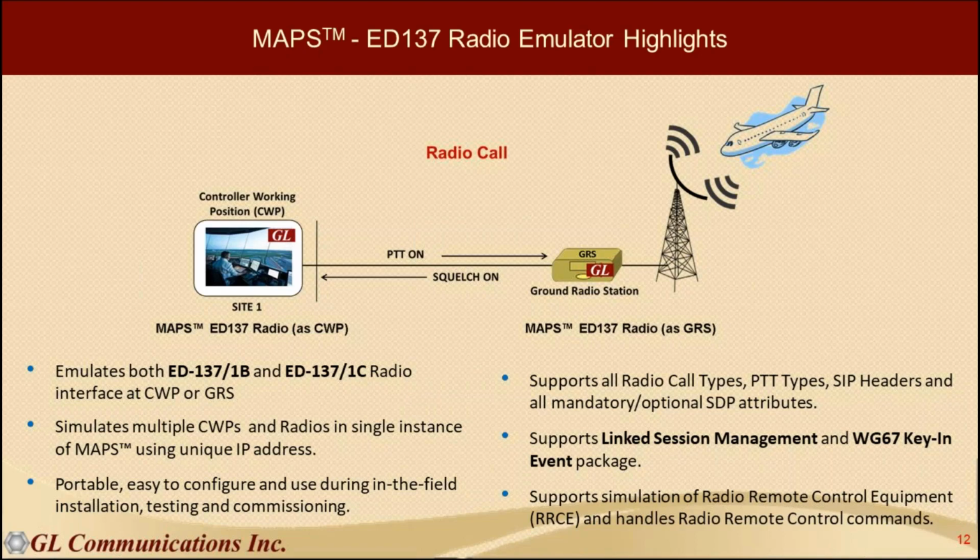Okay, it can be used to test radio interfaces within real CWP, VCS, radio, and radio gateways. It also supports all radio call types, PTT types, and additional SIP and SDP parameters as defined by the ED137 specifications. So all the parameters mentioned in the specifications have been included, and they can be configured per controller or radio.